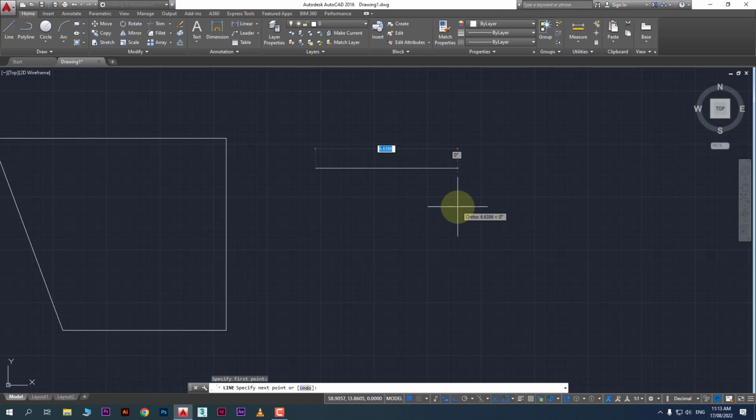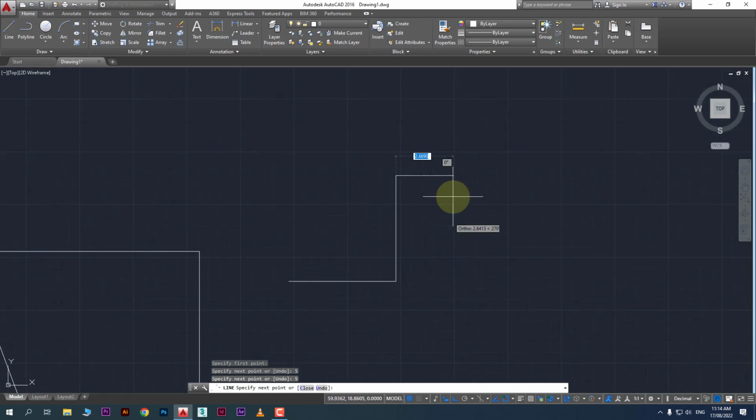So what is the benefit of using dynamic input? Actually it will show you the length of the line, and also the angle. Now if you see this, you can also put in a value, like I want to draw a 5 unit line, and the angle here is 0. If you click here, a 5 unit line has been drawn. Now as you are coming down, you see the angle is 90 and the length is there. Alright, and you can also enter 5 units, then you have drawn the line to 5 units like this.